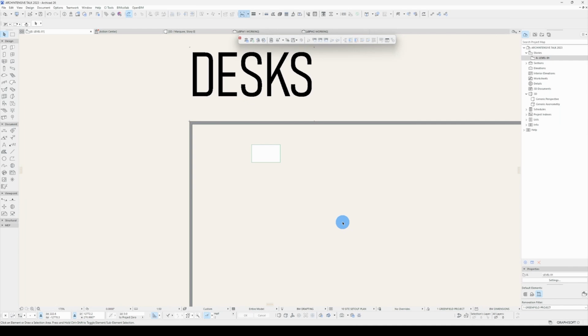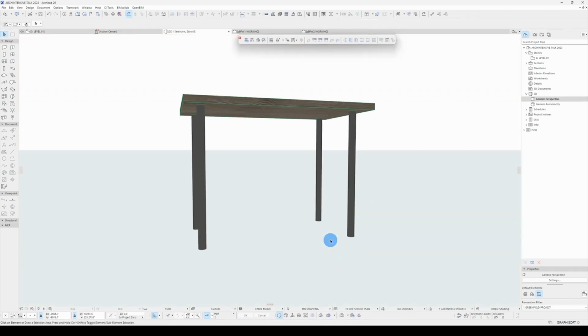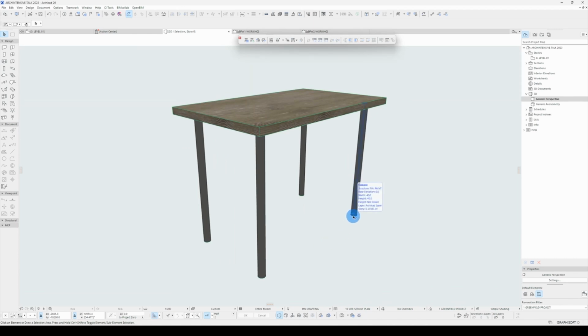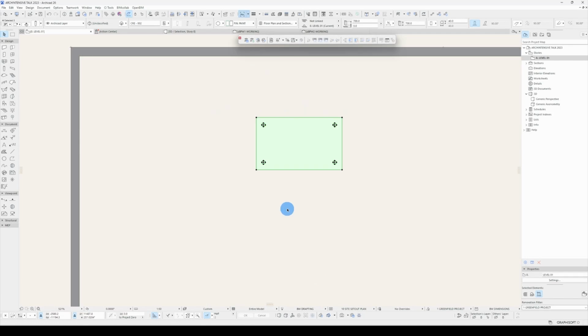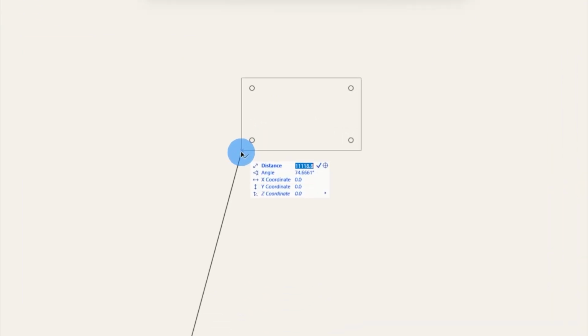This technique is the quickest and easiest technique. However, it also offers the least parametric flexibility. I've created the geometry I want, so my desk has been created using native Archicad elements, in this case just columns and a slab, and I have the materials applied that I want in the final result. The object origin will be determined based on the file origin itself. So the next step is to move my geometry around the file 000 point.